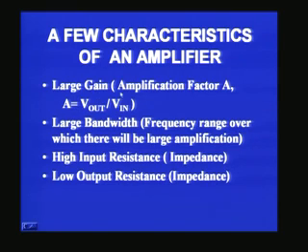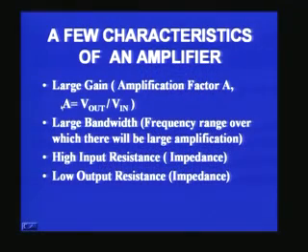So you can see I mentioned that only for a voltage amplifier the gain is V output by V in, because there are other types of amplifiers, for example current amplifier, power amplifier, etc. In the case of a current amplifier, the gain factor will be I output divided by I input. Or in the case of a power amplifier, A will be equal to power output divided by power in.